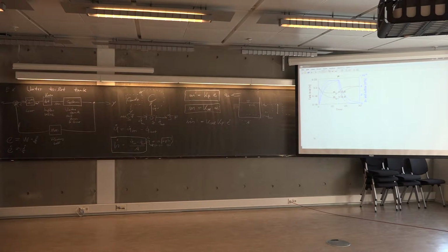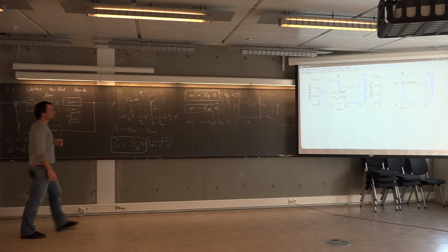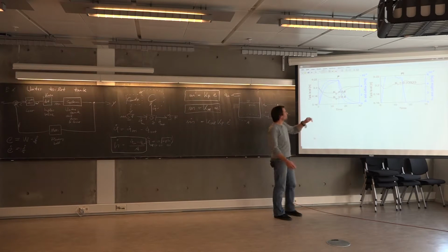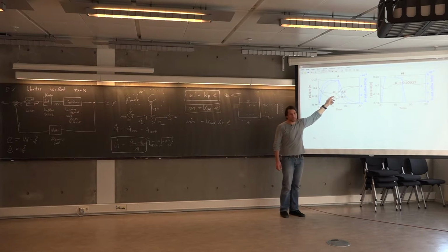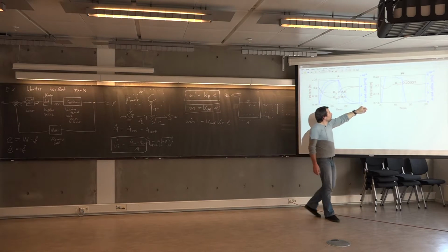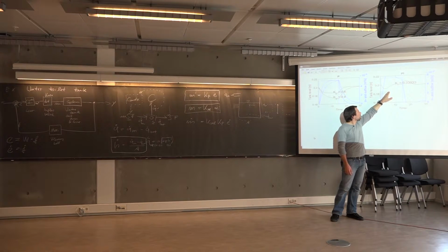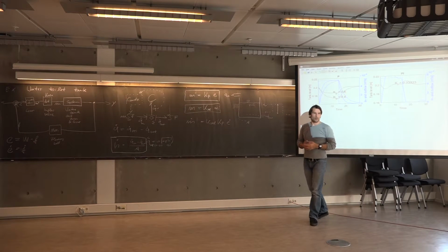If we then rerun this example using an intermediate value for Kp, I think in this example here Kp is something in between, 0.6, then the integral part of the controller equation eventually gets rid of the error, as previously mentioned.